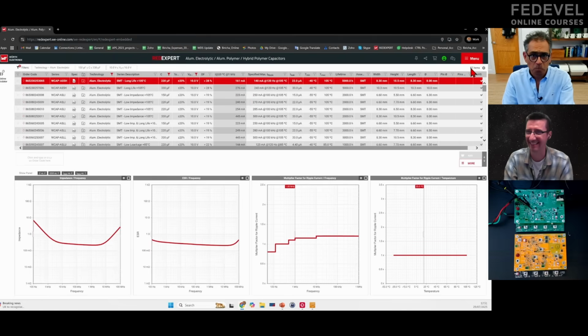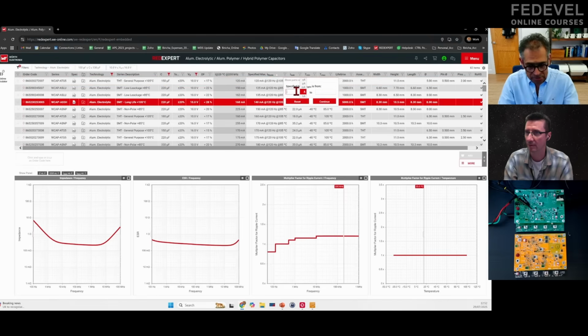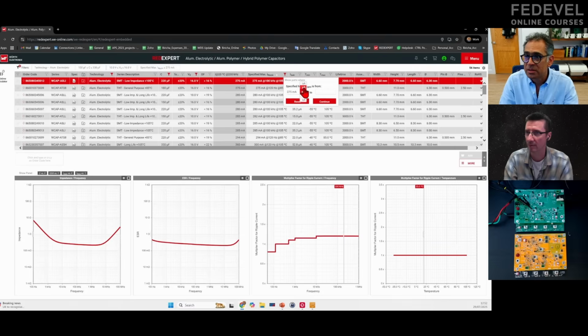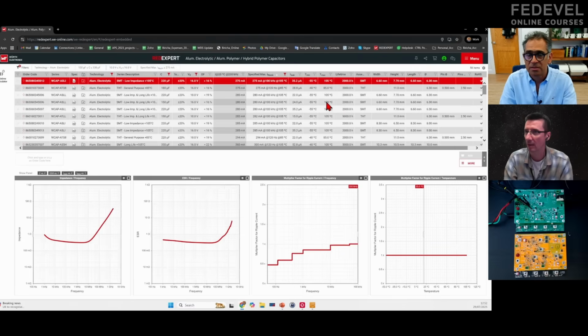Okay. And then if you remember, we said that the ripple current rating had to be, was it 275, I think? It was 275. Yeah, okay. So including my margin, it was going to be 275, right? So let me go to specified maximum ripple current, and I say that I want it to be bigger than 275 milliamps, right? It goes down to 56, yeah?